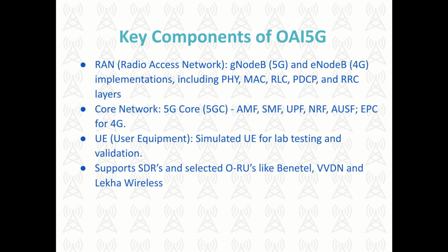That's where some limitation is there, because at present they support only the National Instruments USRP family of SDRs, and certain models of Benetel, VVDN and Lekha Wireless ORU have been found working with their RAN.